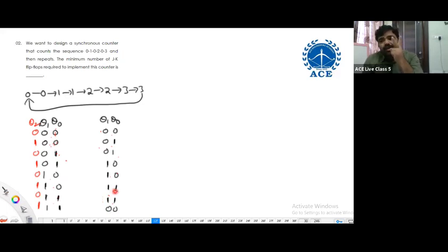Then what should I do? Add 2 extra bits. To differentiate 4 possibilities, 2 extra bits. And if I want to differentiate 5 possibilities, I need 3 bits. 5 to 8, 3 bits. 8 and above up to 16, it is 4 bits, and so on. You can understand it here. Here, I'm using 1 extra bit because we have only 2 possibilities to be differentiated.